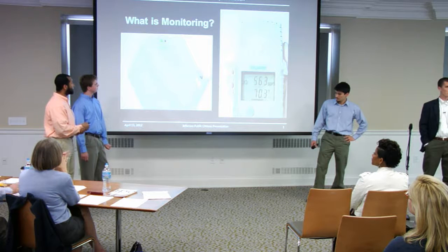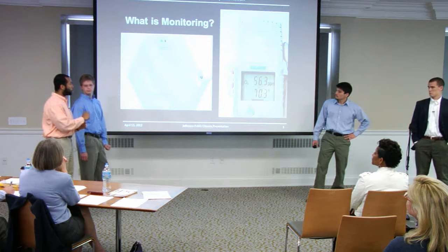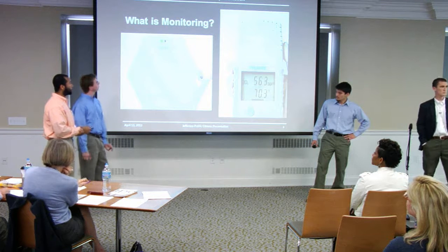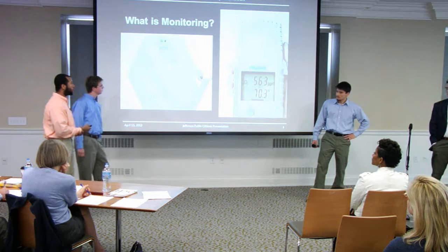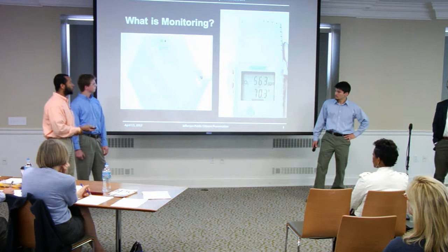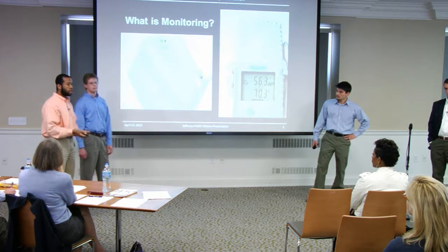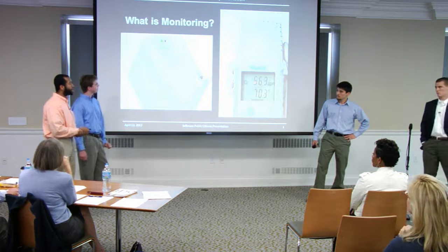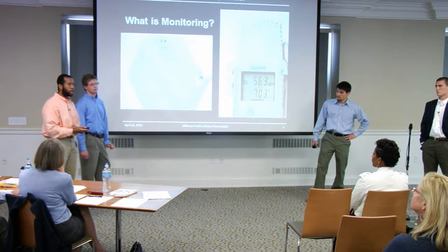And basically, this sends data to a wireless computer that's located upstairs. So it gives us a lot of flexibility to have a lot of sensors, but not a lot of wires. This over here is a carbon dioxide sensor, just an example of what a sensor may look like. This device measures carbon dioxide and temperature. We would want to see carbon dioxide data, for example, to see how well the heating, ventilation, and air conditioning unit is working. If the CO2 levels are really high, it could mean that the HVAC system is not circulating enough air from the outside.